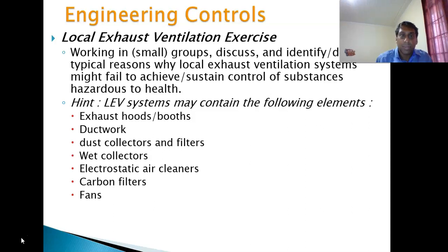Right, saying that the issues with the LEV system, you can get shortcomings with, for example, the hoods, the position, the ductwork possibly being squared, fan speed. Those would normally be the reasons for the loss of control of contaminants.